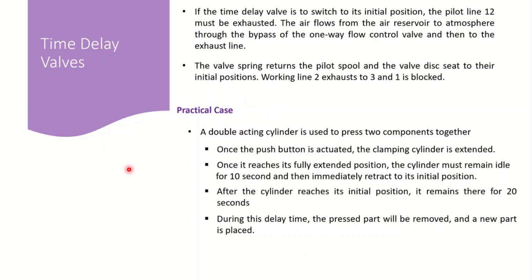so now let's say we have the time delay passed, right? The system should return back to its initial position, right? Because we applied the delay, the pneumatic actuation actuated the directional control valve. We had the directional control valve in its second position. Now let's assume the delay is gone, the actuation is gone. Basically, the directional control valve should return to its initial position, and as we have a spring return, the spring should return that directional control valve to its initial position.